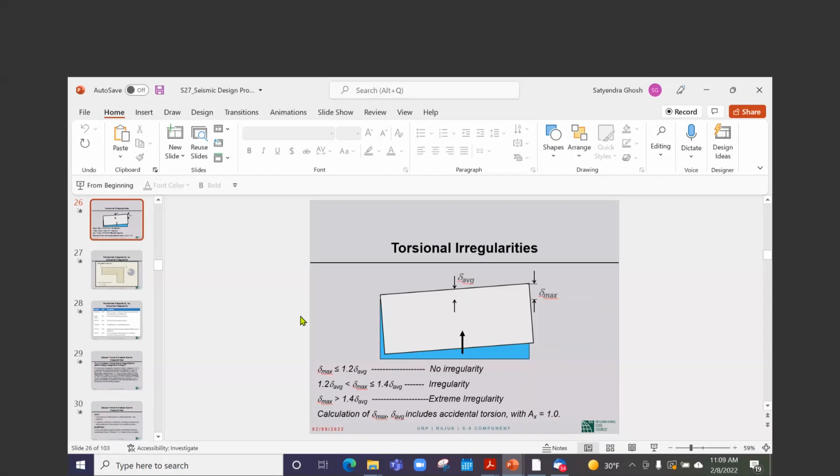So to identify soil type like SD, SC, or SA in BNBC, we have to take the average SPT value up to 30 meters. However, if the standard deviation is very high, can we use the average SPT value? This you should ask Dr. Abedin when he comes. I'm not the right person to answer that question.